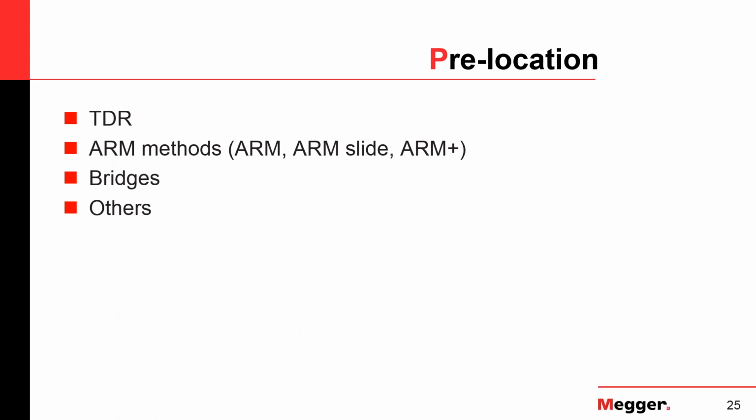What is prelocation? Typical methods are TDR. Then you have the arc reflection methods, which there is a few of those nowadays. Then you have bridges, which unfortunately I had to leave out of the presentation, so I cannot really say anything to that.